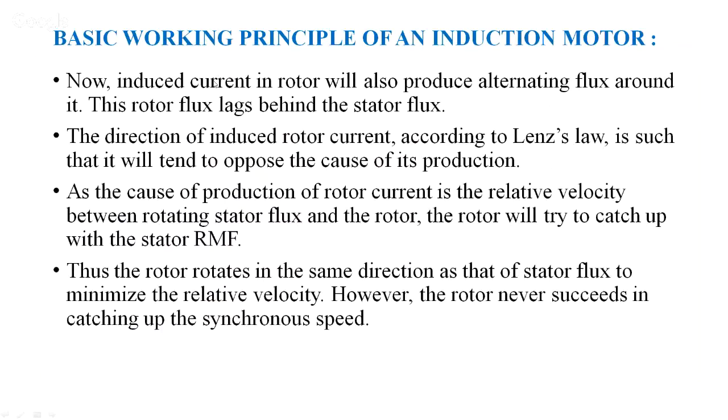Now, the induced current in the rotor will also produce alternating flux around it. So we have learned that any current carrying conductor sets up a magnetic field around itself. Now, in the air gap, there are two magnetic fields. One is due to the stator windings.